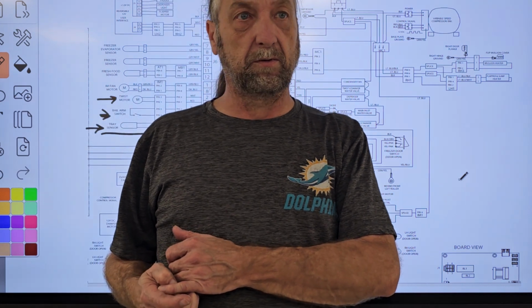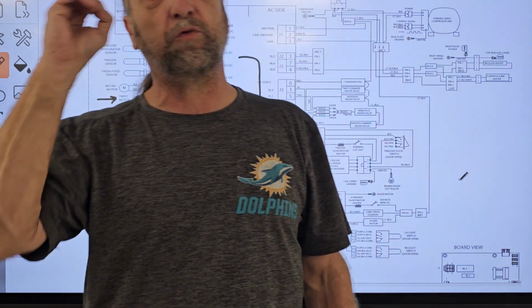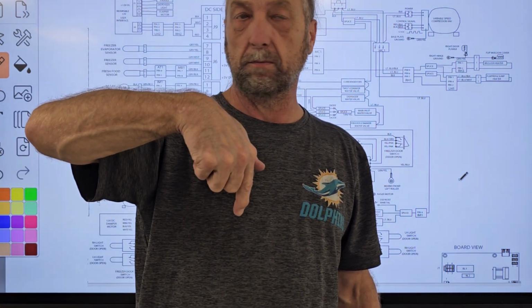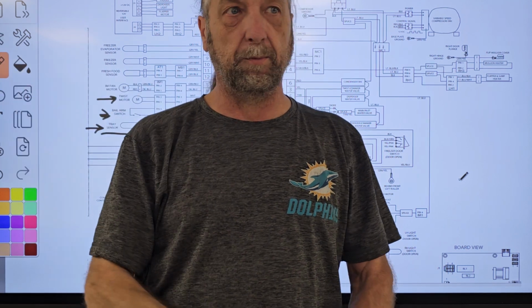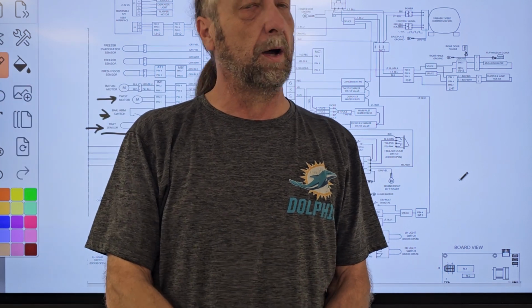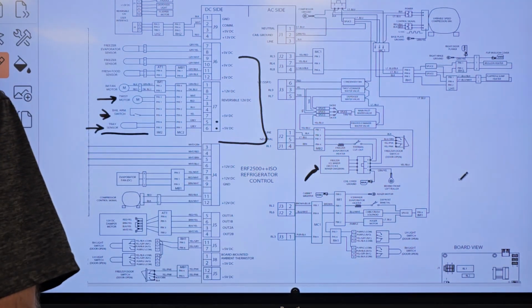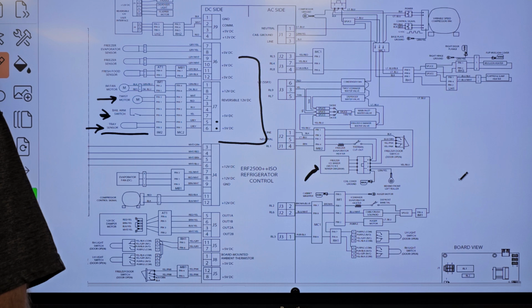Diagnostics. We have to go into diagnostics and try to force that water valve to bring water in. Okay? What if no water comes in? The valve is bad. Huh? The water valve is bad then. The water valve's bad? Yeah. Could be. Water can be turned off at the house.